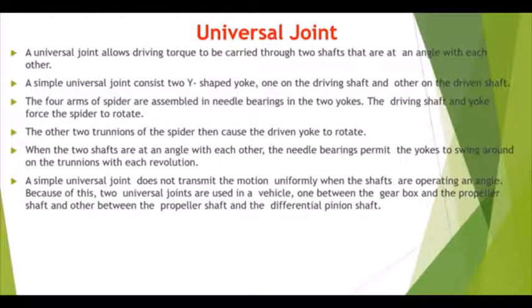Majorly, when two shafts are made at an angle, that is very important, and this is usually done with the help of your universal joint. The drive shaft doesn't rotate with a constant angular speed in relation to the driving shaft, as it moves at 90 degrees to the movement given to the shaft when you have locking with the help of this universal joint.